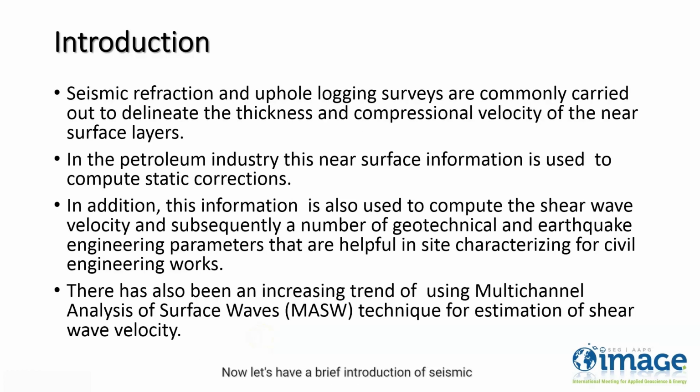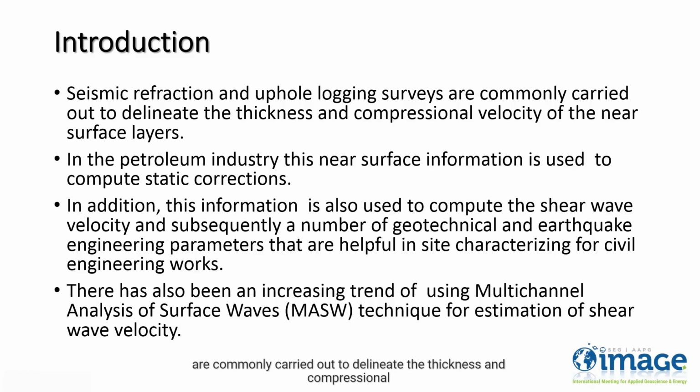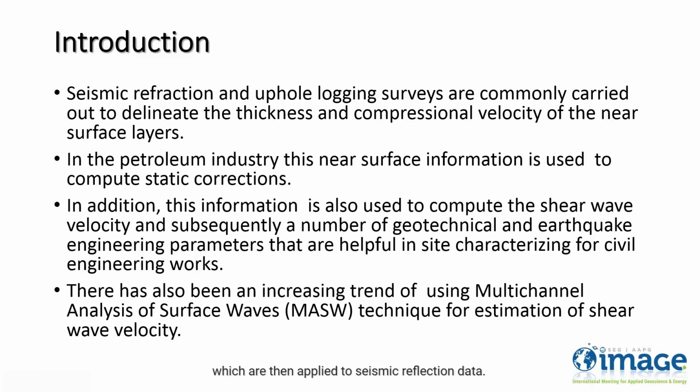Now let's have a brief introduction of seismic refraction and uphole logging techniques. We know that seismic refraction and uphole logging surveys are commonly carried out to delineate the thickness and compressional velocity of near-surface layers. In the petroleum industry, this near-surface information is used to compute static corrections, which are then applied to seismic reflection data. In addition, this information is also used to compute the shear wave velocity and subsequently a number of geotechnical and earthquake engineering parameters that are helpful in site characterization for civil engineering works.